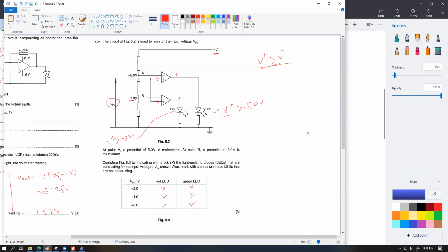জি স্যার। তো স্যার 2 ভোল্ট যদি প্রথমে হয় তাহলে 5 - 2 হচ্ছে 3 ভোল্ট। না, 2 - 5 মানে হচ্ছে -3 volt, because you're going to do V plus minus V minus, you're not going to do V minus V plus. আচ্ছা আচ্ছা আচ্ছা। বুঝে গেছে? And sir, for the green one it has to be greater than +5 volt. Beautiful. That's because of what I wrote.